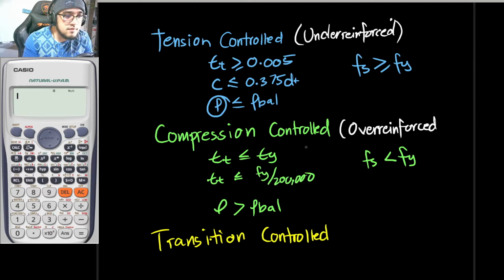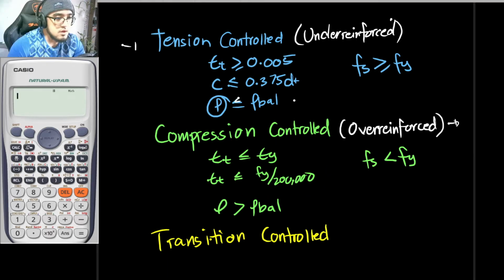So just take note of this guys. What this implies is that dapat daw yung strain sa outermost fiber, or the outermost steel, does not reach the strain of its limit. In other words, the most critical rebar should not exceed the strain limit. It is as simple as that.